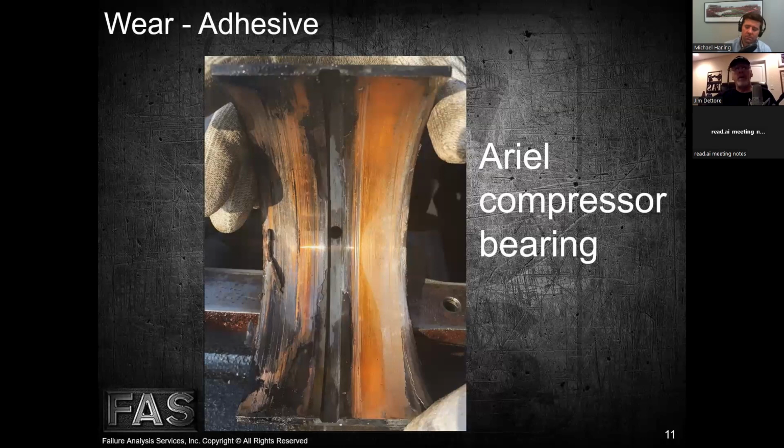So keep it in mind when we say that the lubricant is contaminated, we're not just talking about abrasive contaminants. If we have a water pump failure or an oil cooler failure and we contaminate that lubricant with coolant or with water, well, the coolant or the water are only designed to lubricate one thing in the engine, and that's the seal in the water pump. It doesn't work real well when we start mixing it with lubricating oil.